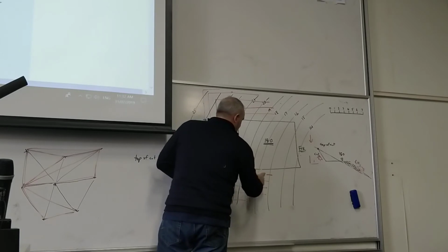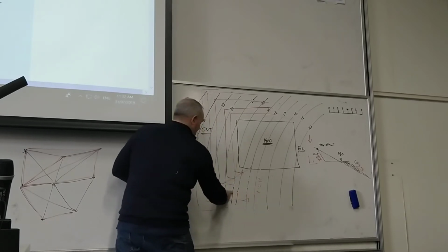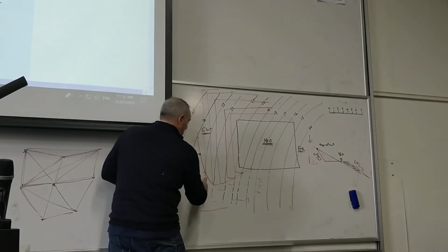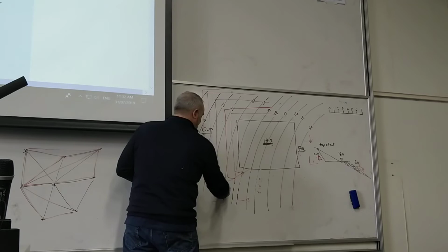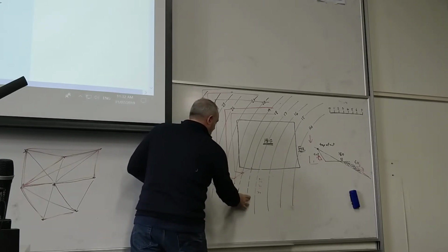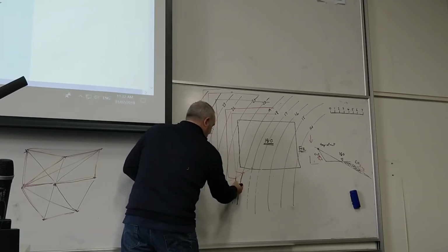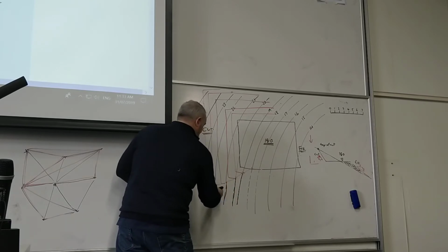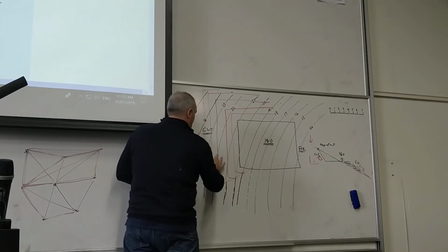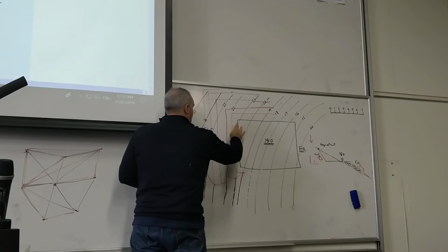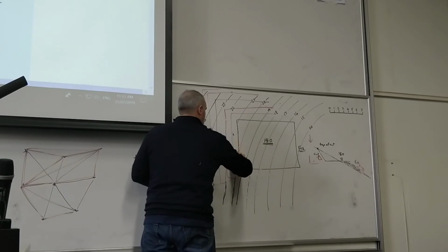None of these lines are needed outside of the cut. Not at all. None at all. Because they are design contours. And they're inside this piece here. What is required outside is these lines here. Because they are existing ground, and if they're outside, the ground doesn't change. But if they're inside, they disappear. Might stop using my finger. Turning everything black back to the desk.